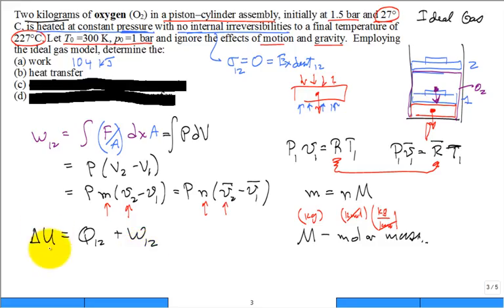It is definitely not enthalpies when you write down the first law for a closed system. It's internal energies, and it's a common mistake people make. All right? So you've got to get your equations right. Now, there's another small error: the minus sign, because the sign convention is Q in, work out. So in this problem, we just calculated this work. You can just leave it and substitute in for that work value.